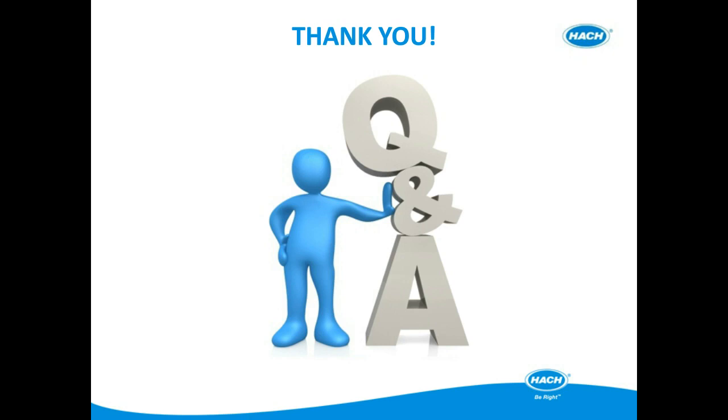Okay, that's great. We've got another one here, Martin. Is the Hach TOC online analyzer suitable for oily refinery effluent? Yes, it is actually. There are a number of things that we would need to look at in the effluent itself, but the main issue with oily samples is cross-contamination from one sample to another. But we do have cleaning processes on our sampling systems which can use scouring with air and water to flush those residues away to ensure that we're getting a representative sample.